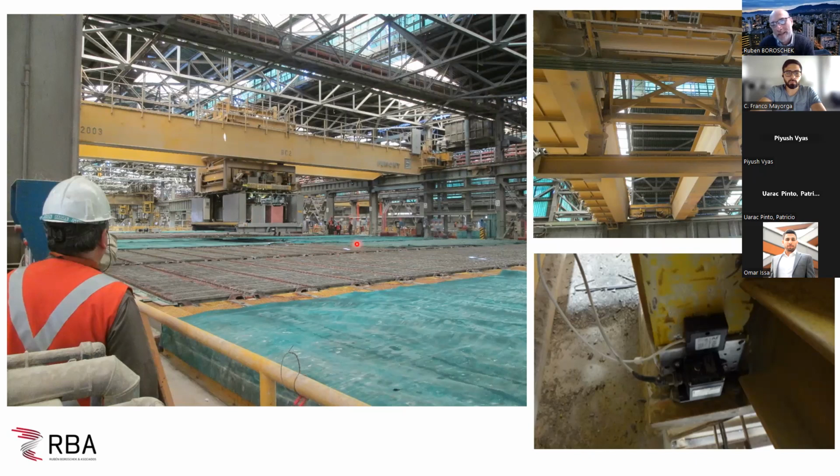So in this case, we capture and detect the irregularities that produce the fall of the plates. And the solution to this type of problem is stiffening the supporting beam and correcting the irregularities on the rail. And after that, everything was working okay.